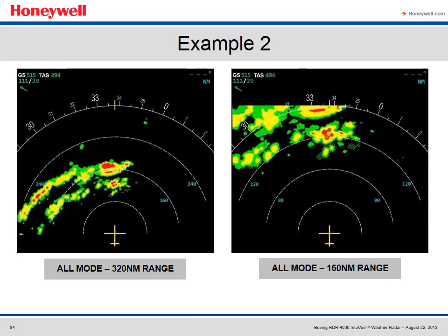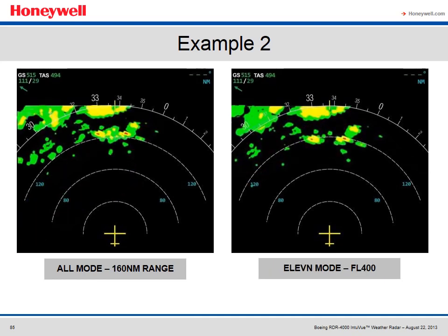The auto mode picture by itself doesn't seem to provide much hope, but looking at an altitude slice at flight level 370, there are two small, higher reflectivity cells on each side of the aircraft's track. Looking a little higher with a constant altitude slice at flight level 400, there appears to be a potential way through. These cells are still more than 120 miles away, so there remains considerable ambiguity regarding the precise echo top of any part of the weather.